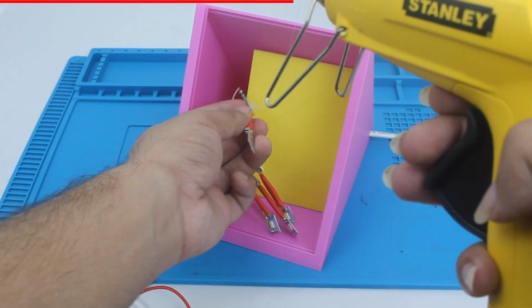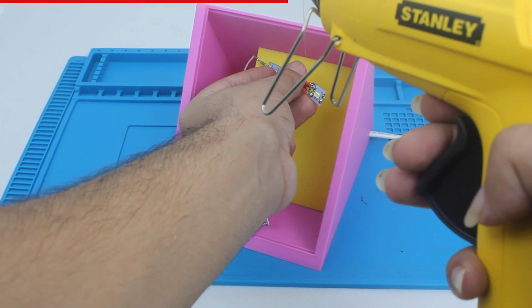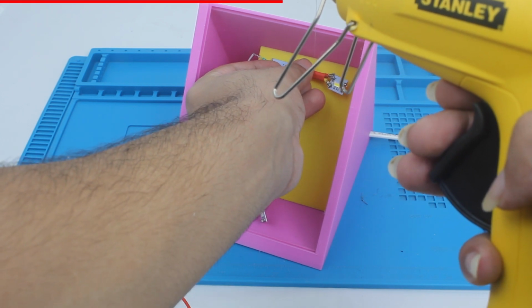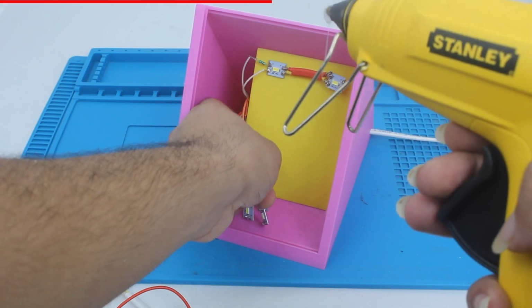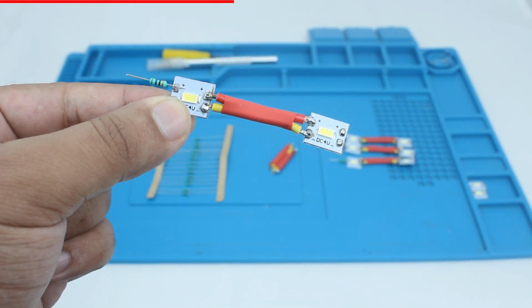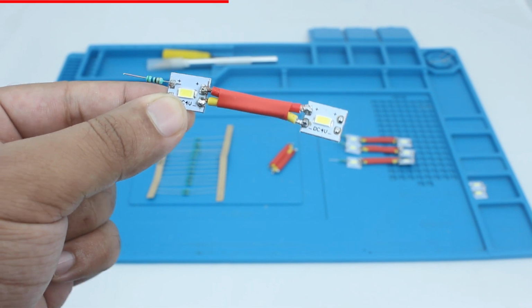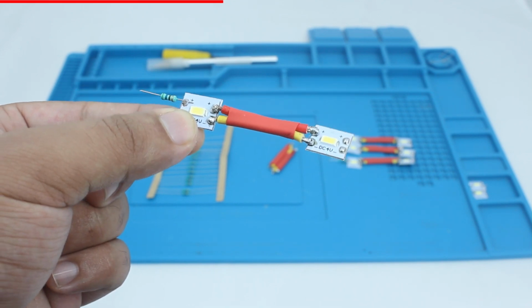You have to be very careful regarding the current draw and the heat produced. USB ports only give out 500 milliamperes of current. So if you aren't sure of how much current your LED bulbs would require, I'd always recommend you use a multimeter to find out exactly how much. I purposefully underpowered my LEDs by using a relatively large 500 ohms resistor because I would only use these lamps as night lamps and I really do not want to risk a fire.